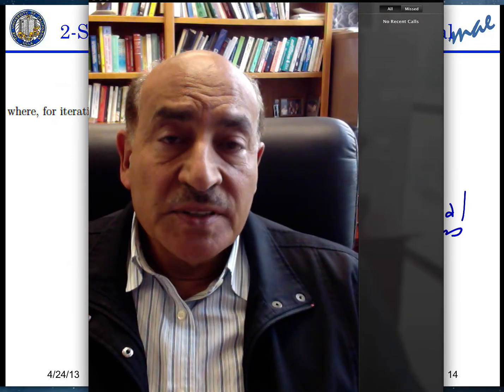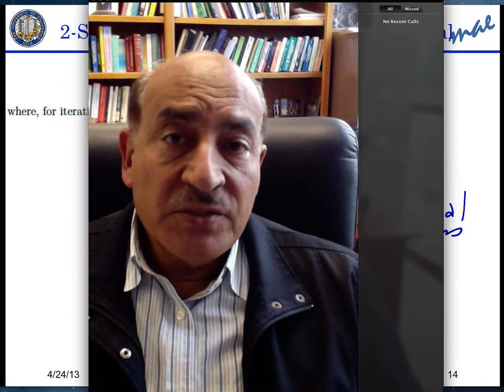So the alloy at that composition will have the lowest melting point, and therefore I can utilize this composition to melt it very quickly, and then I can add some other things to get it away from that composition if needed. So the idea of the eutectic is an important idea.